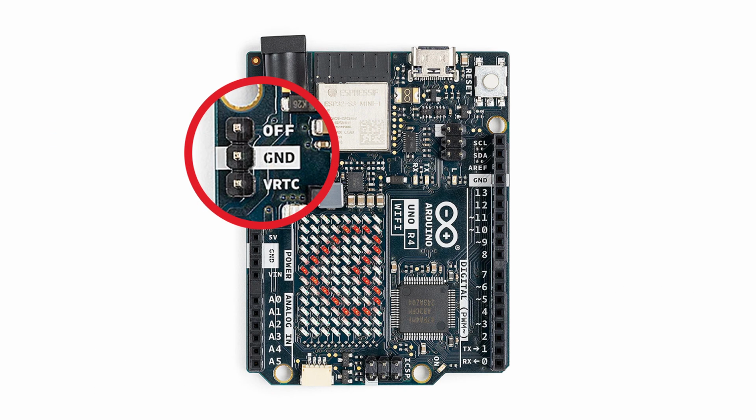As long as we power the Arduino, it will keep track of time. As mentioned previously, if we apply a power source between 1.6 volts and 3.6 volts to the VRTC pin, the RTC chip will continue to function even if the main power source is cut. This is how a lot of modern-day electronics keep track of time. They have a separate power source, normally like a coin cell battery, that powers an RTC chip.